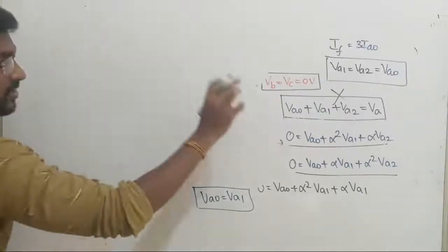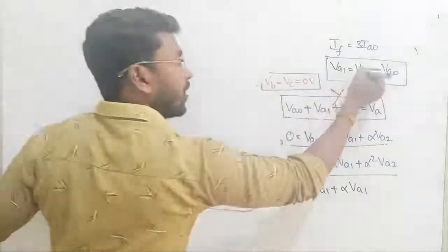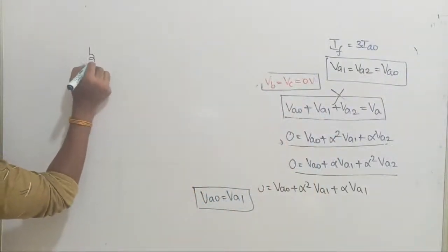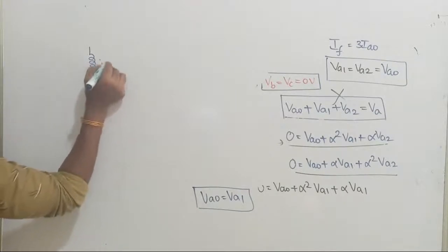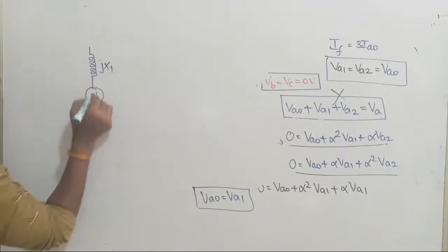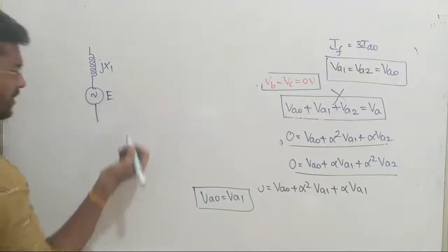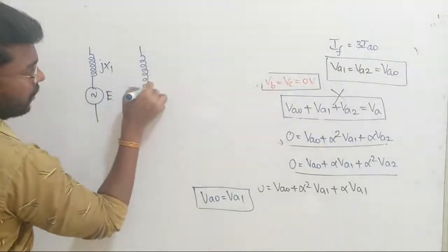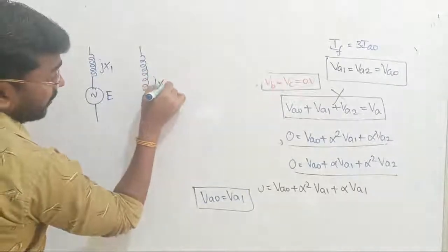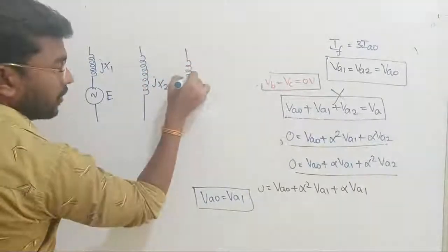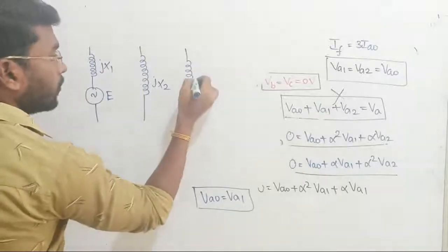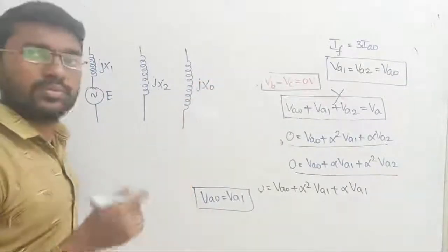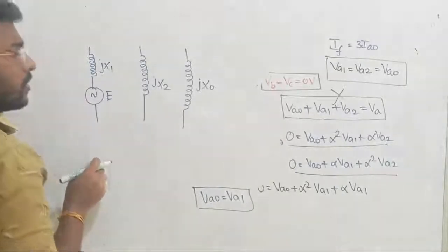Now what are we doing? We have gathered the information that the positive sequence, negative sequence and zero sequence are all going to be in parallel. How will you draw the positive sequence? Positive reactance j times x1 with the positive sequence voltage. Anyway, E or VTH we know. Next, negative reactance. Just observe. Don't memorize anything. I'm repeating, right? Even me too. In this area we should never memorize, right? But if you solve problems, it will register in your mind. That case will be different, right? Fine. Shall we continue now?